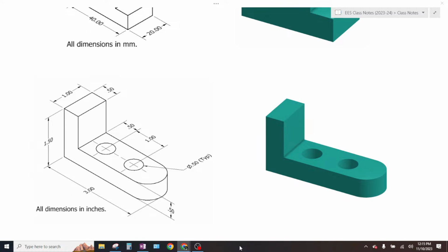The teeth on the bottom that are bigger have straight edges on the inside. You use those to measure stuff by going on the outside. The smaller teeth up top have their straight edges on the inside. Those are for measuring gaps on the inside, like this. Like if I want to measure the internal width of this hole, I would use the small teeth on the top. In general, your straight edges are what should be touching whatever you're measuring.